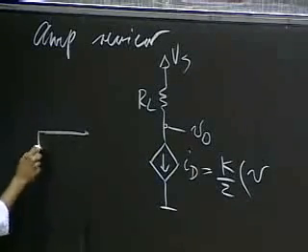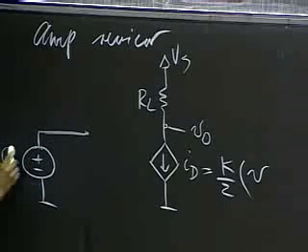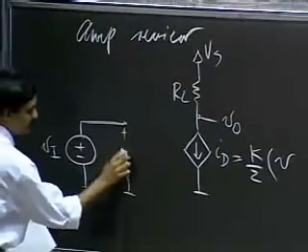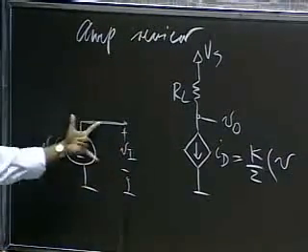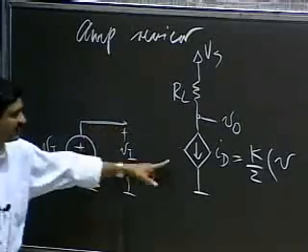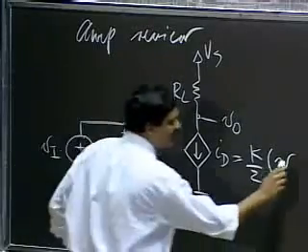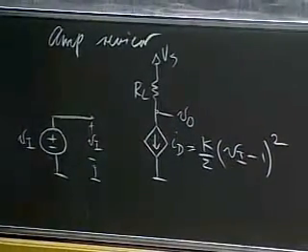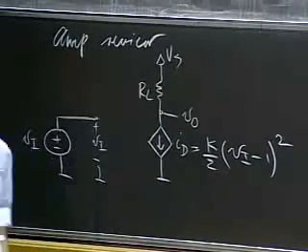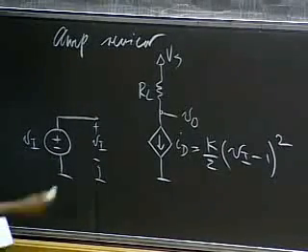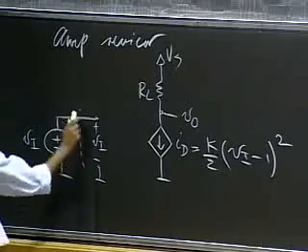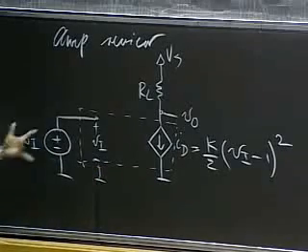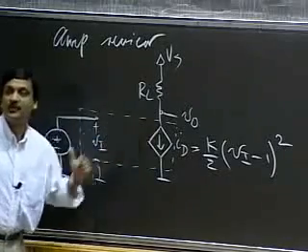So some voltage VI. And so these two were the control port of the dependent source. And a VI was applied there. And I showed you a simple amplifier built with a dependent source that behaved in this manner. And again, I'll keep reminding you, just remember that the dependent source is actually this box here. Okay? The control port and the output port.